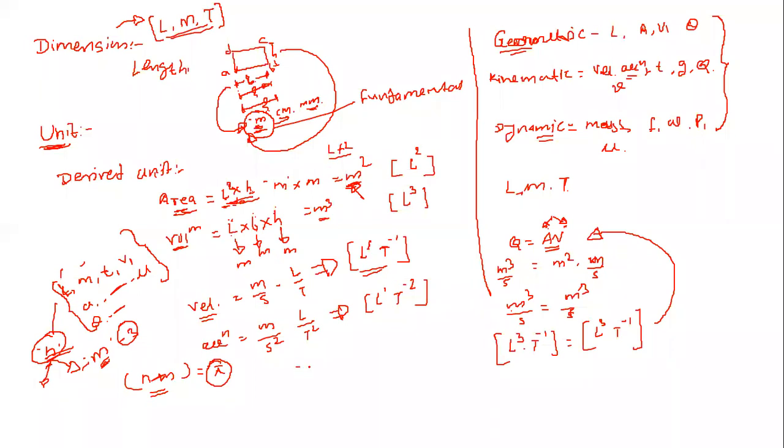It means suppose that, for the time being, we have a number of parameters involved in a physical phenomenon, say the physical phenomenon of an aircraft crashing. In that, suppose the total number of variables involved is 20, and out of those 20 variables, the number of fundamental physical quantities included therein is 3. That is, m is equal to 3. Then these 20 parameters we will be able to arrange into non-dimensional groups, called pi groups, equal to n minus m. That is n as 20 for this case and m as 3. Means we will be able to arrange those 20 variables into 17 non-dimensional groups, and those non-dimensional groups are called pi groups or pi terms.